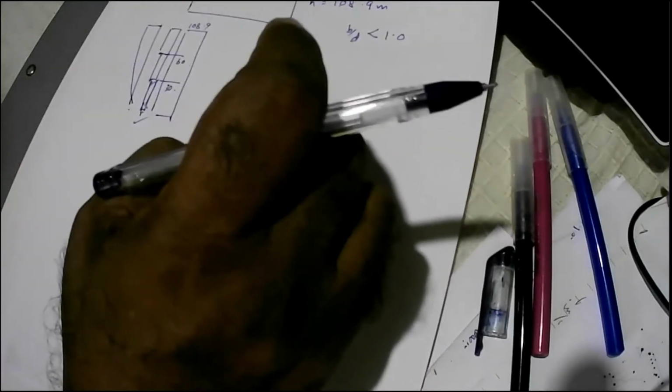Because I'm going to do a manual calculation, I'll divide the building into 3 components over the height. So I'm going to have 3 different velocities, whereas on the rear side, or leeward side, it's a constant velocity, whereas on the windward side it is variable.